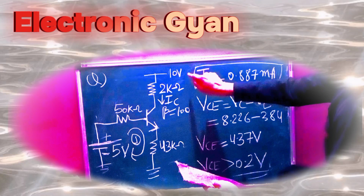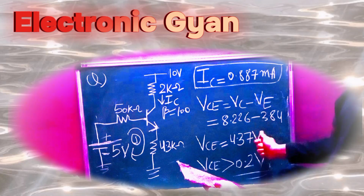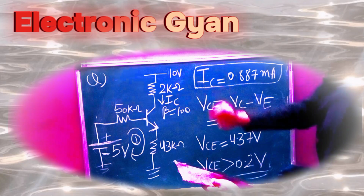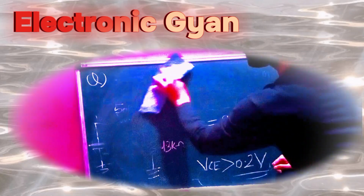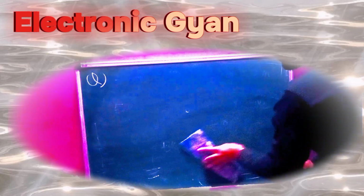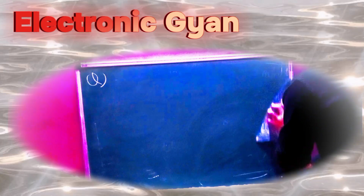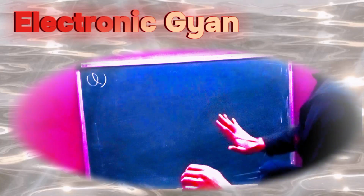Supply voltage by 2 is how much? 5 volts. So it is coming less than 5 volt, which means it is stable. It is thermally stable as well as it is operating in the active region. So let's see. Now we are going to find what? We are going to find the small signal parameters of the amplifier, which is very important to draw the small signal equivalent circuit.